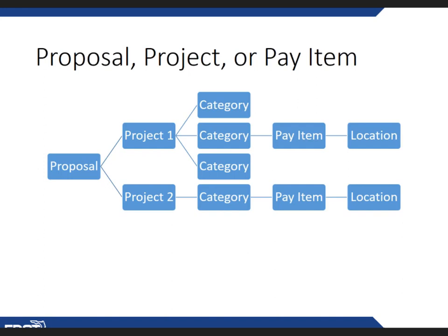And again, for your signing, if you have signs that have lights associated, we have the feedback signs and signs with flashing beacons. So any of those that have electrical power for a sign would be in your signing plans, your signing category. And under no circumstances should I see pull boxes loaded in the roadway category.